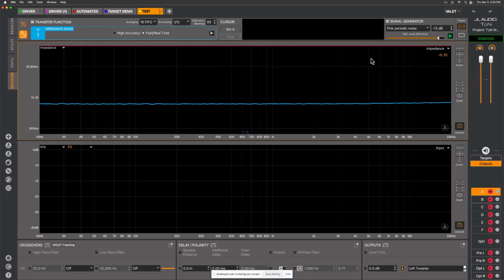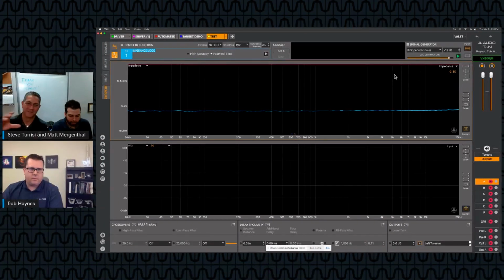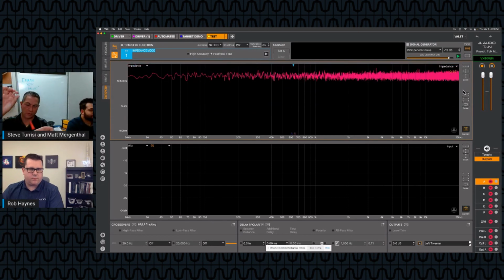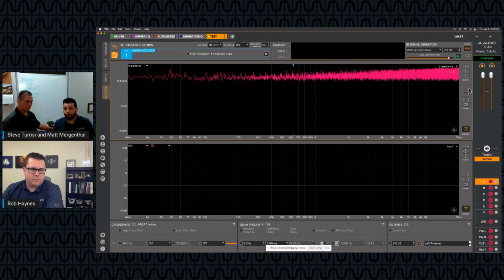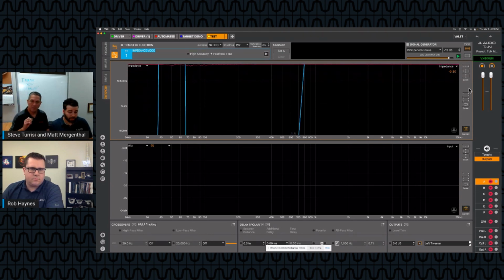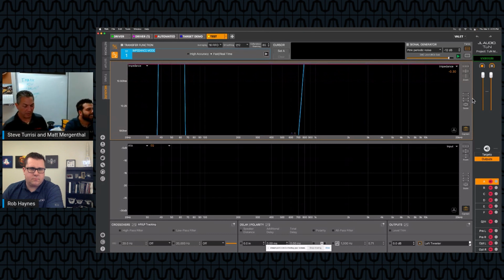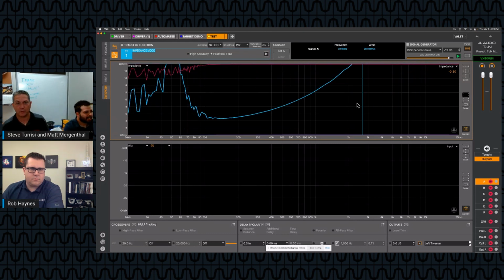So as we said before, Max is really, really close. So we're going to take the resistor out, and now we can measure speakers. You got it? We can? We can. Oh, okay. So we're just going to connect the probes to the speaker, positive to positive, negative to negative. Or if you're feeling like you want to do something different, go right ahead. You may be able to hear the periodic pink noise coming through the speaker too.